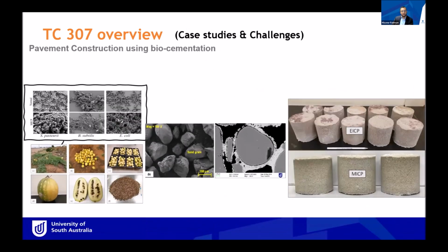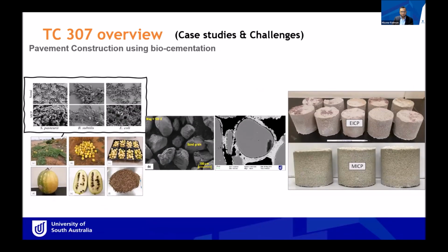Biocementation in Australia is getting popular, and there are some large government projects supported for base course material improvement. I have some research on sand. It's not only base course, these slides are based on sand. We can use some bacteria, particularly Sporosarcina pasteurii.